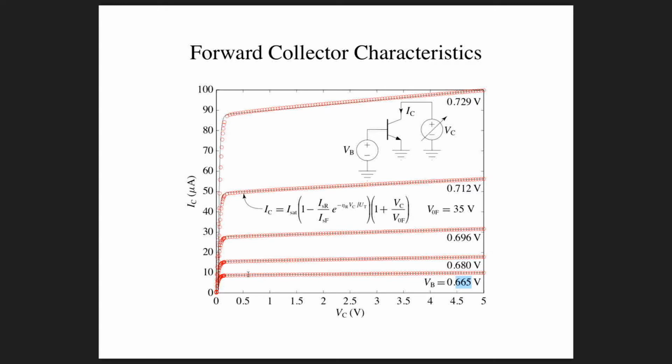And so where is the collector voltage greater than 0.665? Well, it's everything to the right of where my cursor is here, roughly, right? And so you can see that's here. And what's to the left of this point? Well, to the left of this point, the collector base junction would be forward biased. And so formally speaking, to the left of this boundary is the saturation region.